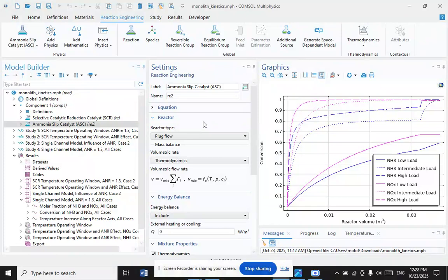The regeneration process occurs at route speed or higher than can generally be attained on city streets. Vehicles driven exclusively at low speed in urban traffic can require periodic trips at higher speed to clean out the DPF. If the driver ignores the warning light and waits too long to operate the vehicle above 60 kilometers per hour, the DPF may not regenerate properly, and continued operation past the point may spoil the DPF completely, so it must be replaced.